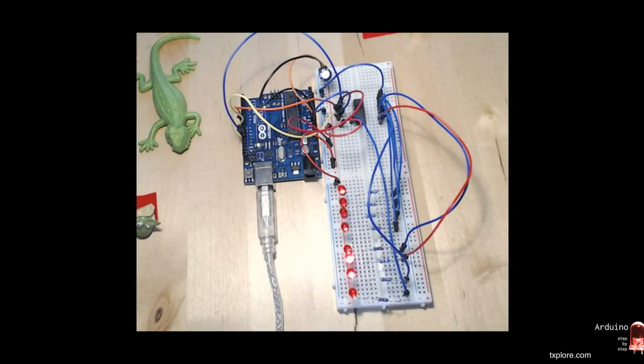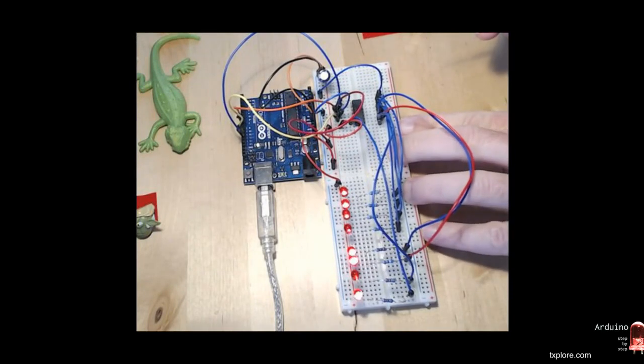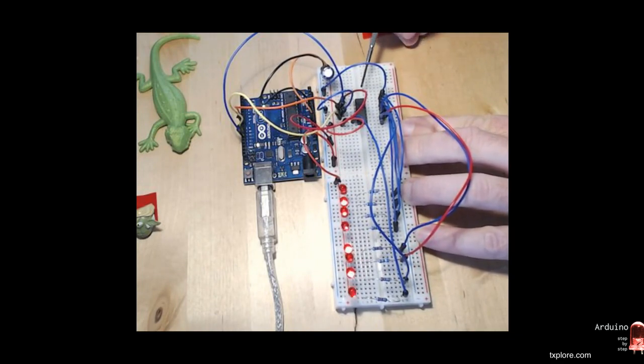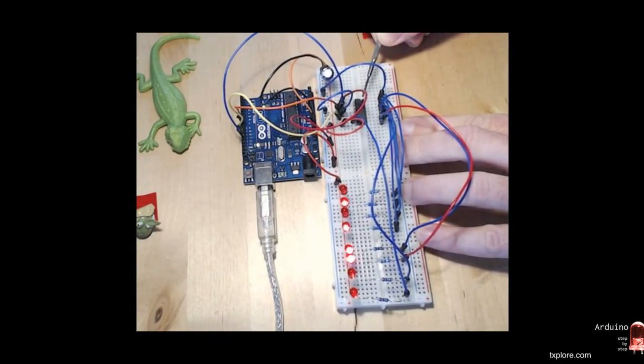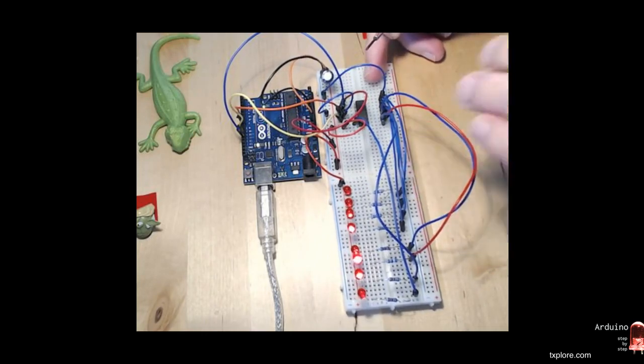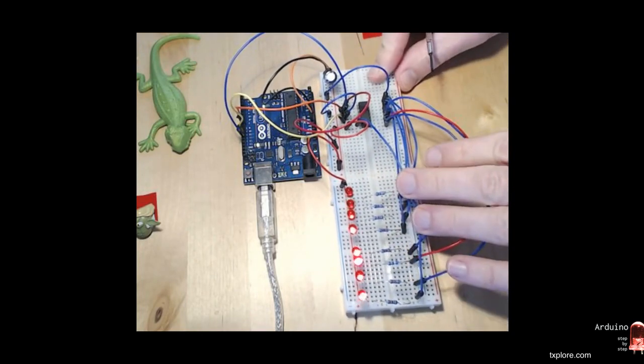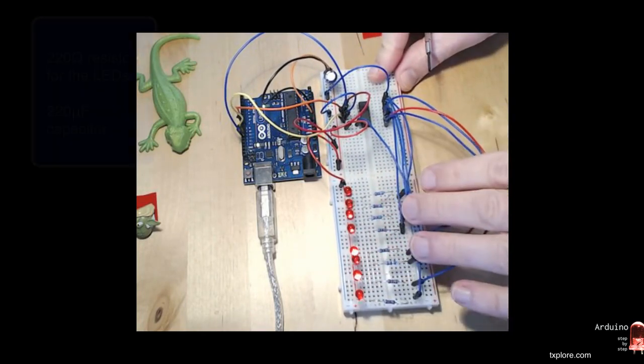Let's have a look at this circuit now. I always start constructing circuits with lots of wires like these from the component that the wires tend to aggregate to. So in this case, it's the shift register, the chip right here. So I plug the chip into one of the breadboards.